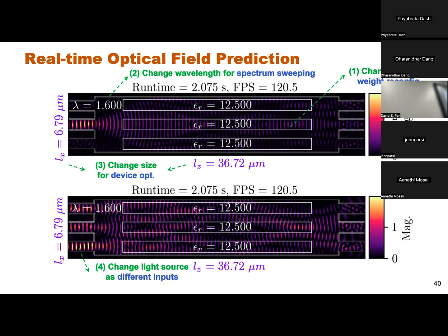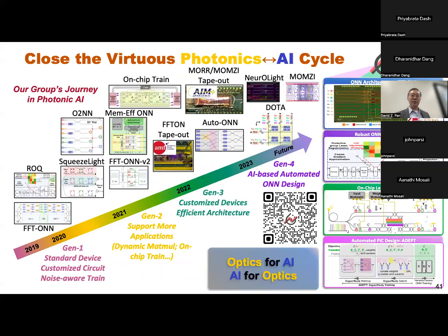But the most advanced one nowadays is so-called inverse lithography, ILT. They even do source and mask co-optimization, because to print those structures you have to do hundreds of rounds of this kind of optimization. Imagine if you are using very detailed simulations, it's so expensive. Anyway, this is related, not directly photonic, but a related field. So let me try to conclude.